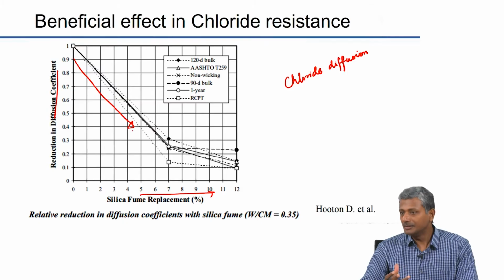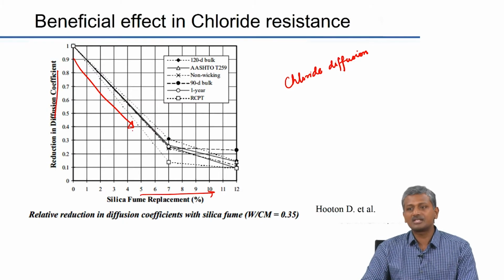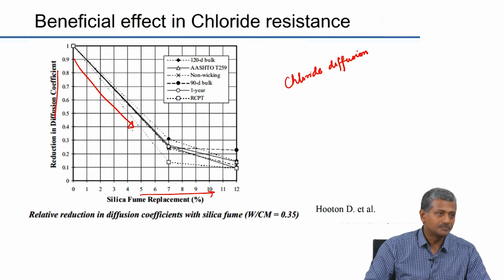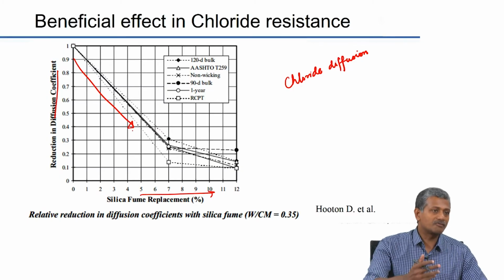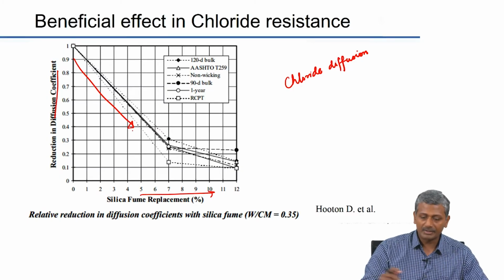So, this is actually a true positive result. In the case of RCPT, you may get a false positive also, but for the most part it also reflects the fact that your concrete is more durable with silica fume.